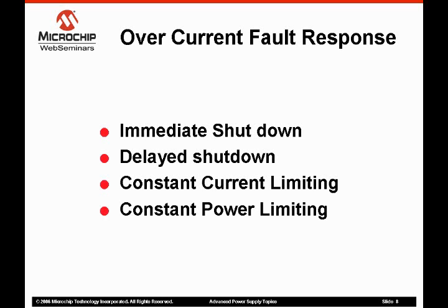3. The power supply can enter a current limited mode. The full rated current is delivered to the load. The output voltage is determined by the load current and the impedance of the load. An issue with this response methodology is that the power supply is providing high power to a load that may have experienced a failure. This could become a fire hazard.